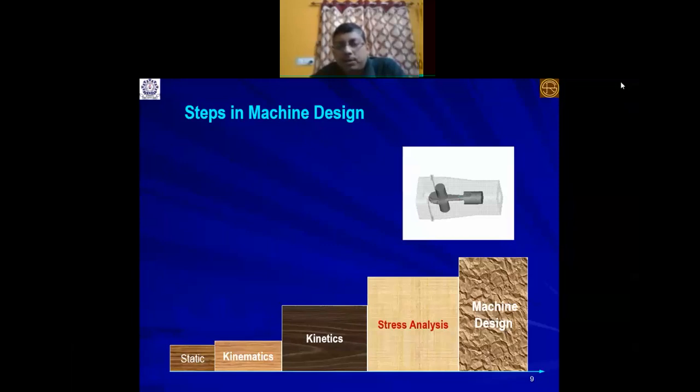You create a joint there, like a revolute joint or a prismatic joint, and you give the input. You give the motion characteristics, like velocity with respect to time. If you give that, then you can find out the time history of the other kinematic parameters, which the software will represent graphically. Basically, inside, the equations are running.